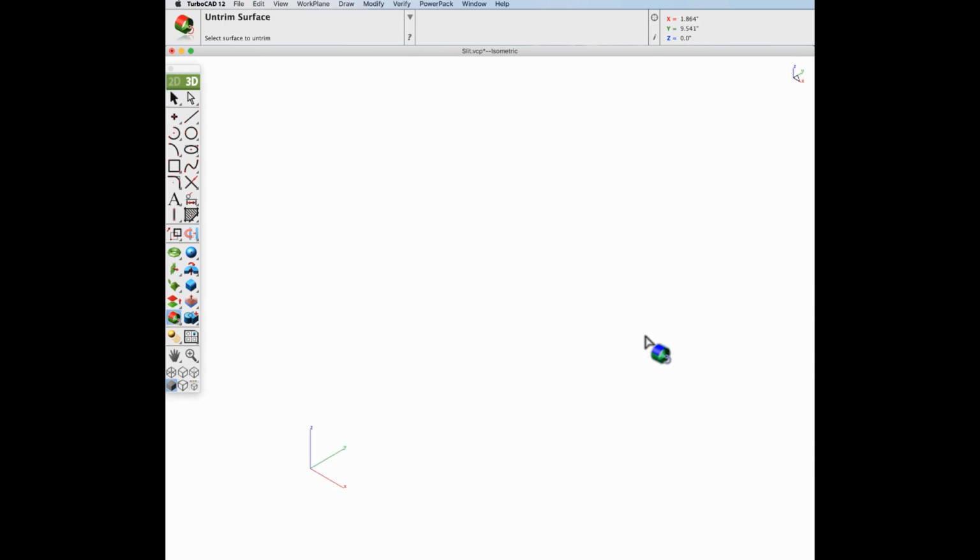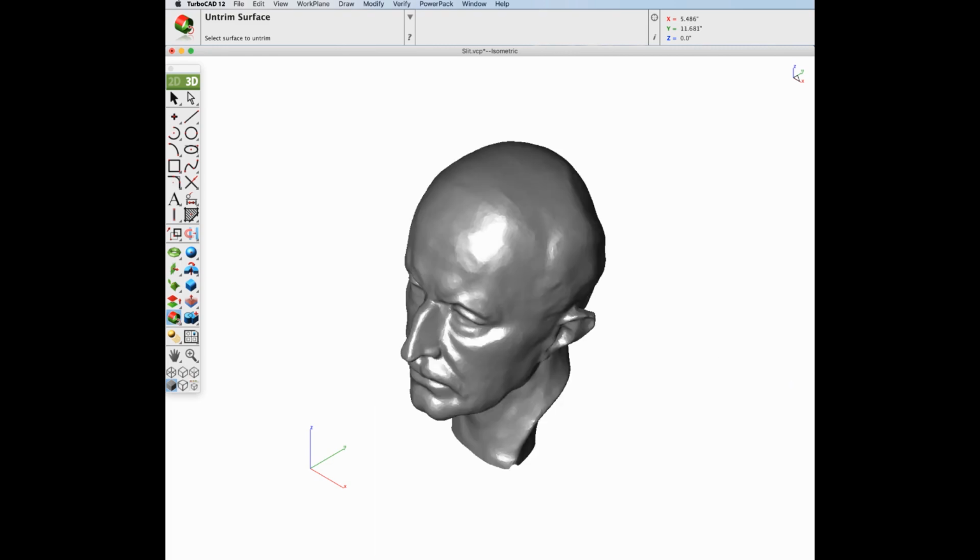The Split Mesh tool is particularly useful when creating parts for 3D printing. By splitting a part into smaller pieces, you can utilize smaller print tables. In this example, we'll split our part into two, add some alignment pegs using booleans, and place it on a printer bed. Let's display our 3D print tools